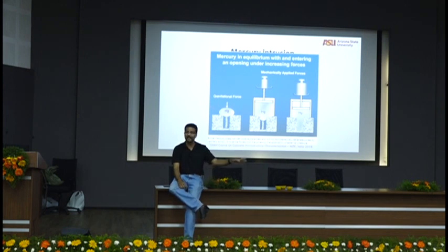Strength is a stress at failure. Theoretically, when something could never fail in compression, what is even a compressive strength? There's nothing called a compressive strength. You talk to a perfect theoretician, a perfect physicist, and tell him compressive strength, he'll say nonsense. When nothing fails in compression, what is a compressive strength? Right? You're failing in other mechanisms. When you're doing compression, you're activating other mechanisms of shear and tension. Things fail in shear, things fail in tension. Okay. And that is why,